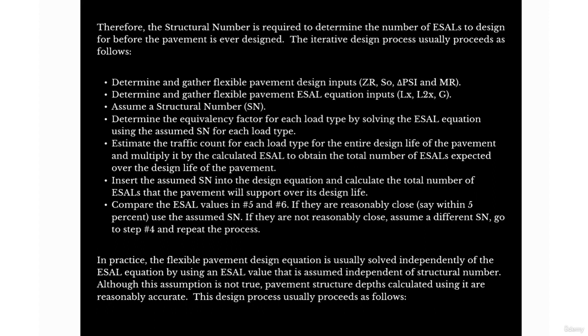Okay, so in practice, the flexible pavement design equation is usually solved independently of the ESAL equation by using an ESAL value that is assumed independent of the structural number. Although this assumption is not true, the pavement structural depths calculated using it are reasonably accurate. So this design process is usually as follows. So let's go through the design process.